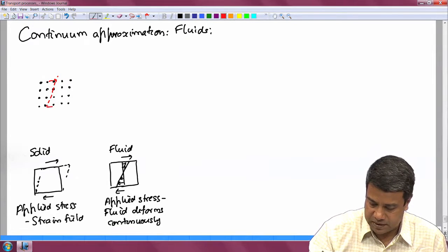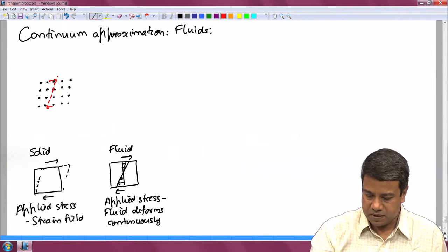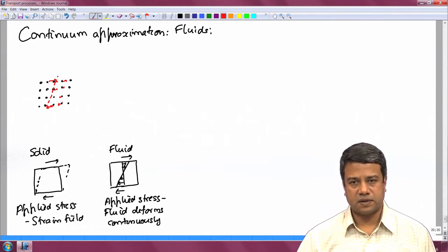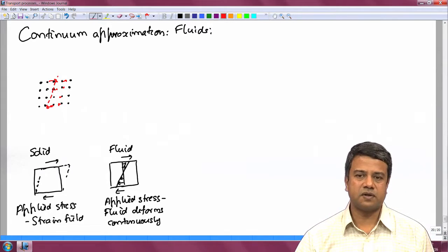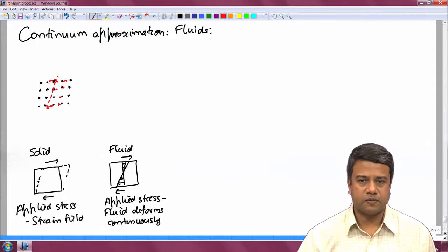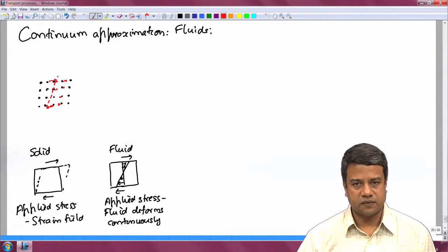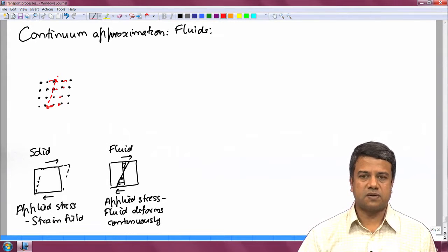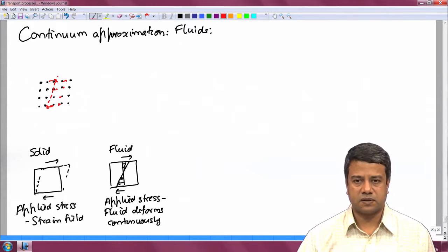if you apply a stress, all the molecules will shift a little bit from their equilibrium positions, and that shift of the molecules exerts a restoring force, because molecules would prefer to come back to their equilibrium locations. So, that shift of the molecules from their equilibrium locations generates a restoring force, and that causes a stress. So, this happens because the molecules have defined locations within a solid.